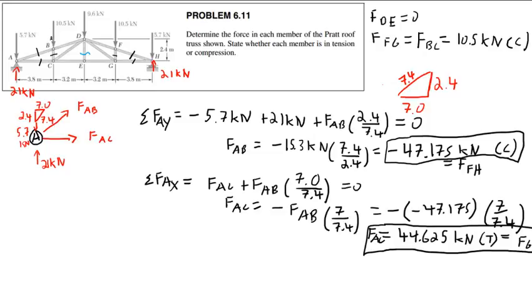Simply because this is effectively two sets of collinear members. If you have two sets of collinear members, or a force and a collinear member, you're going to end up with them being equal. Let me go over here and talk about this a bit. So collinear members. We talked about zero force members, but let's talk about collinear member sets.